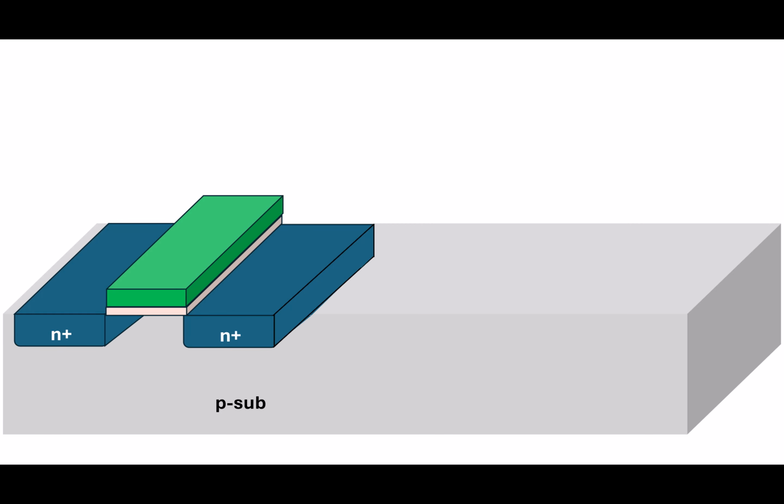So first of all, let's understand how transistors are made. Some of you would have taken some courses already. So what is the base on which a CMOS process is made? A P substrate like this, and then you have an NMOS transistor made like this. You have two N plus regions, and then you have an oxide and the gate here. That's a MOSFET. This is an NMOS.